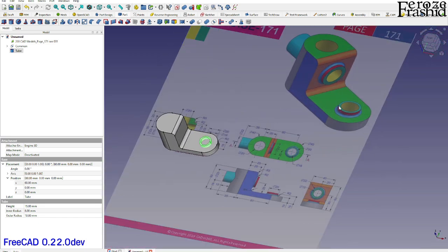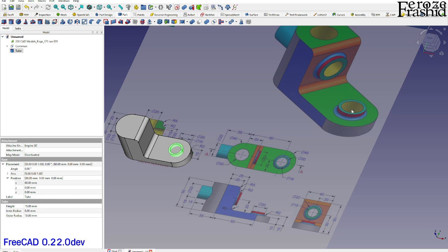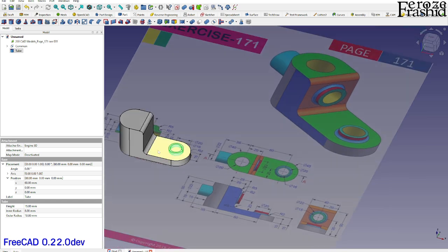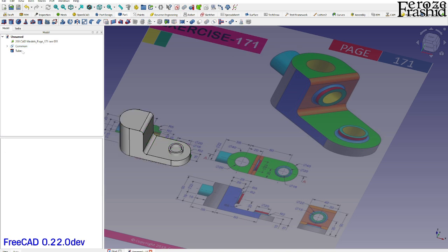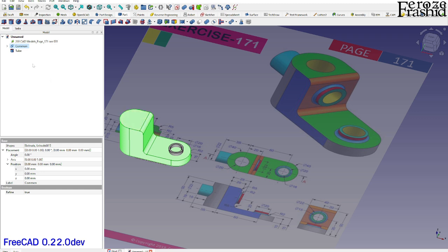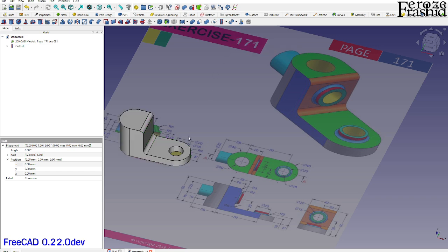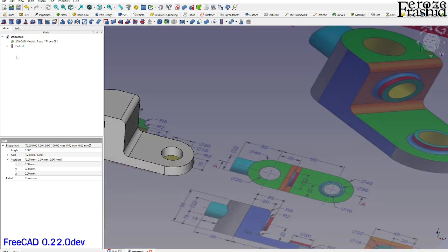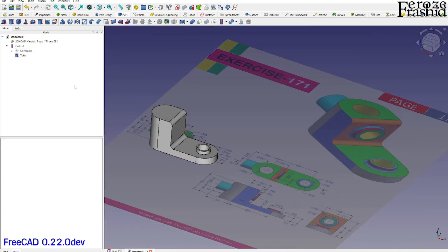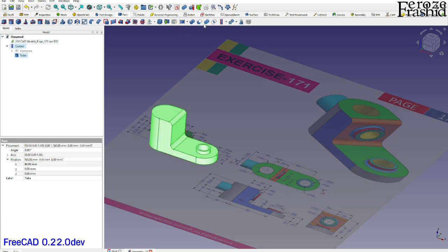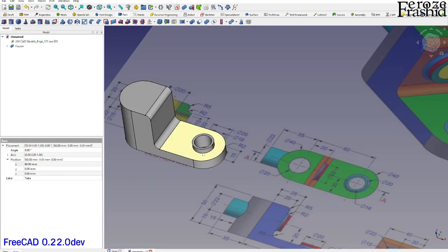And on this main object, what I see is there is a hole that goes through, and we can easily do that by using one of these three functions. I'm thinking maybe cutout for object. So let's give it a try. Take the common, the main object that I want to cut out from, and then take the tube, the second object, and come here, say cutout for object. Now that object is gone, it's right here. I can select that, make it visible, and make these two a fusion. So that is our first way to build this tube.